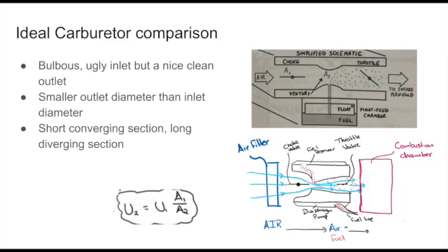The carburetor on our chainsaw differed in many ways from the idealized models we typically look at. One characteristic that stood out immediately was the irregularly shaped inlet and choke valve of the carburetor. Since the fluid that first enters is just air, the design of the choke side should focus on enlarging its area so as to maximize the effect of the Venturi of speeding up the mixture at the throat. Because of this, the choke side of the carburetor is noticeably larger than the throttle side. We don't really care about the flow detaching in this portion of the carburetor.